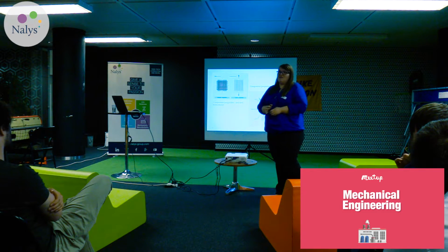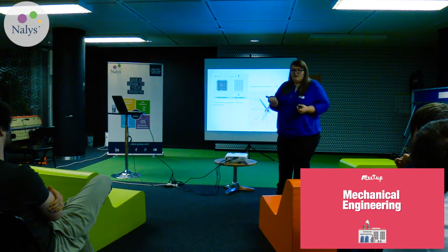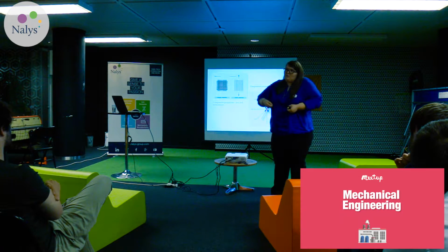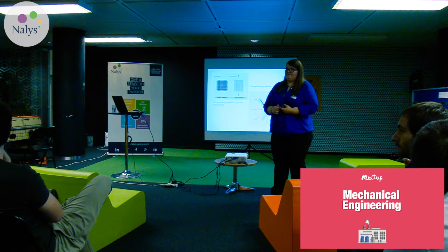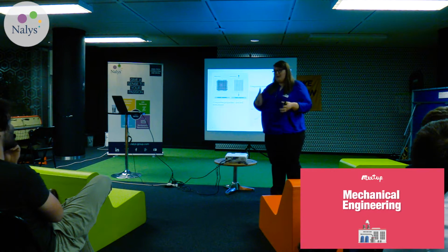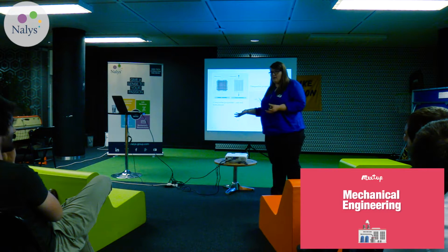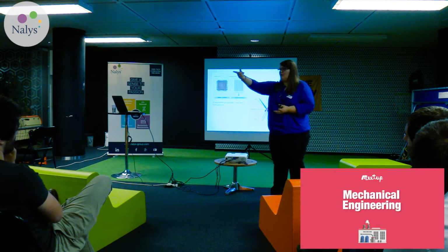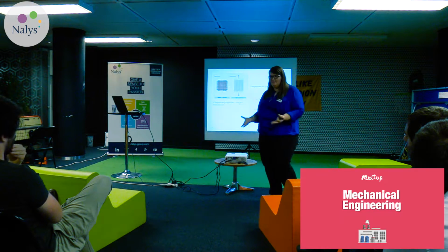The composite in that sense will have the feeling of a plastic, and will be stiff. That's curing, the process of transforming and making the composite. The autoclave, what Mario said, is the oven. Alright.